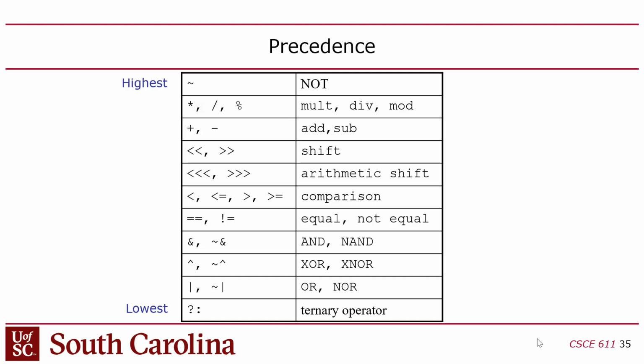So if you use a double equal, then it's assuming that you're just concerned about real binary values, 0 and 1, right? But if you're writing a test bench and you want to compare to, say, a don't care, an X, then you want to use the triple equal, right? Make sense?